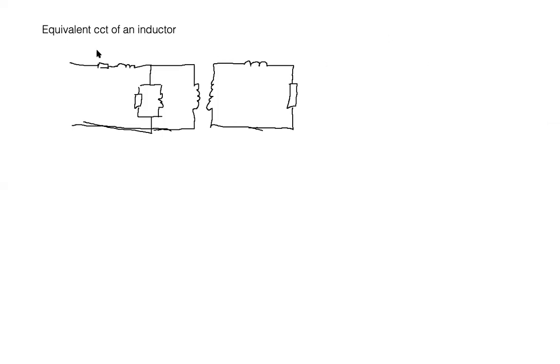If we are going to label this, this is the stator resistance, this is the stator reactance, and this is I no load. The current flowing here is I no load M, and this is jXM, and this is I. You can call this I no load loss, and this is RC.